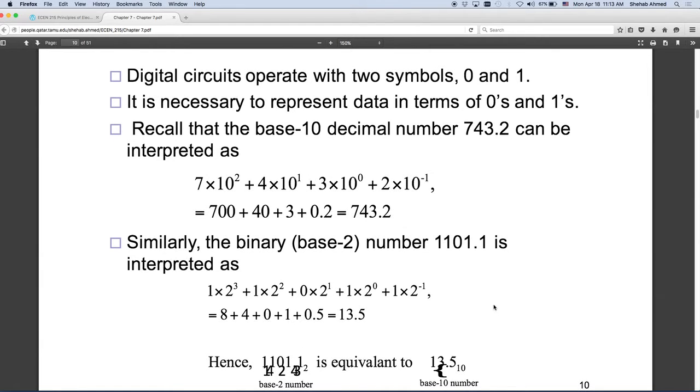Since I know the voltage that will be measured, it will fall between, I don't know, minus 1 volt and 1 volt. For me to represent 1 or minus 1, I need 1 or 2 bits. And we will talk about how to represent negative numbers later, but with 2 bits, that means if I have 1 byte to represent my data, then I can use 2 bits for the 1 or negative 1 representation, and I can use 6 bits for my decimal portion. Right? So it's a decision based on your application.